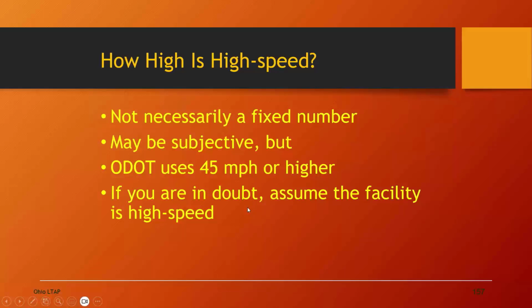That reminds me of another policy we had when I was at the city of Columbus. There are several 40-mile-per-hour two-lane roads in Columbus, like Agler Road, and some other roads up in the northeast part of Columbus. If we were flagging in those areas, for instance, we would use the high-speed spacing of our signs instead of low speed to protect the flagger. So instead of 100-foot sign spacing, we used 350.